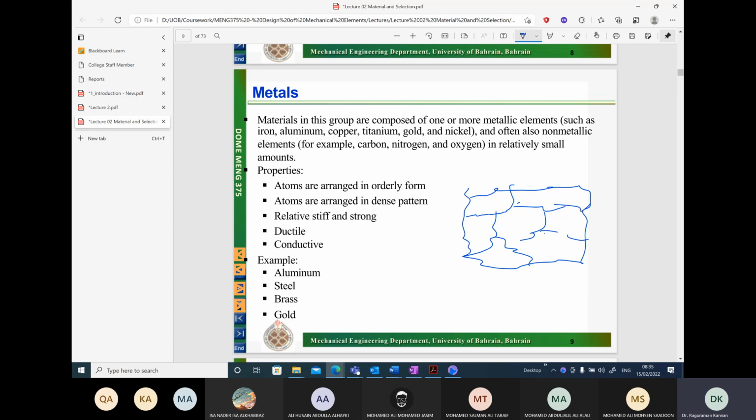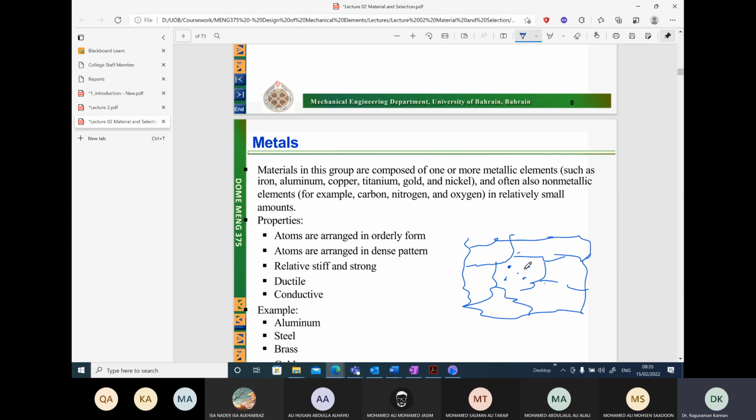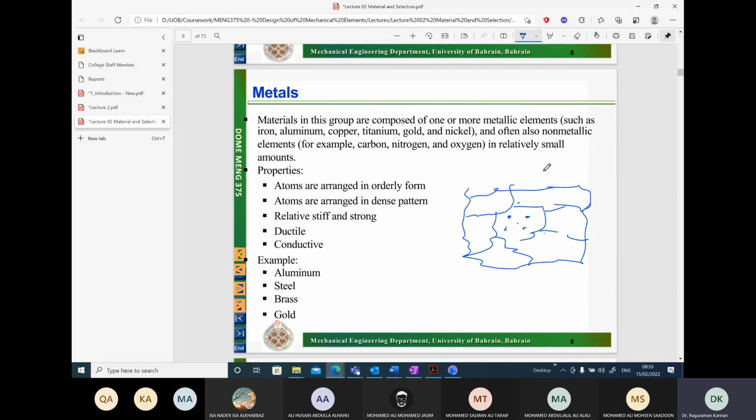If you take each grain, you might see the BCC structure, or in the case of steel, specifically a body centered cubic structure. I'm just drawing a 2D version of the BCC structure. You have the atoms located in particular locations, the nucleus of the atoms specifically, and then you have a sea of electrons around it.